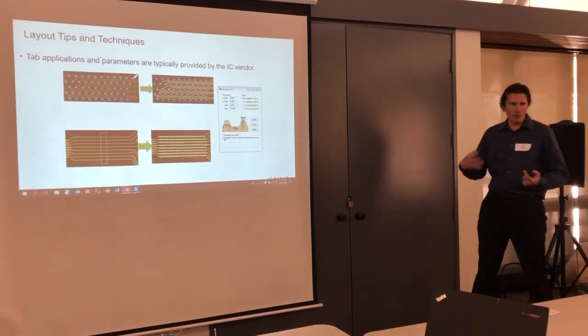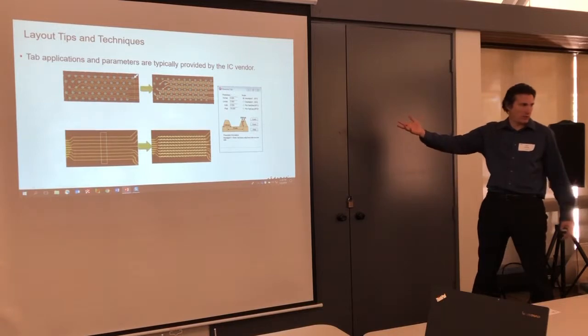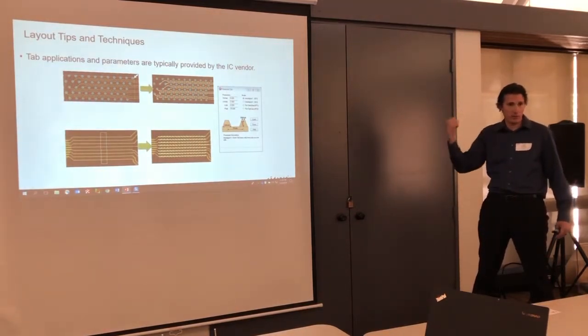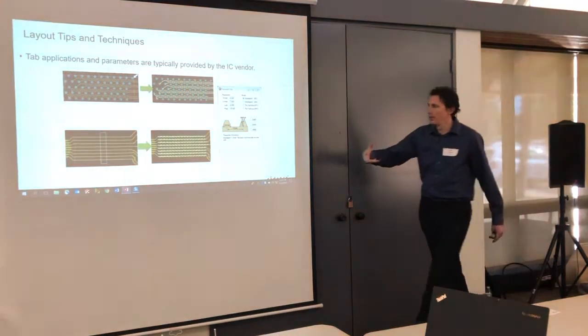And so you would probably never just randomly throw these things on, because you definitely would not get the desired effect by just putting them on thinking, hey, this might help. You probably wouldn't have the space to do it anyway. But what you would get, if you're implementing a processor from a company that requires these things, is in their design guidelines, they would say, hey, for these signals, put these tabs on.